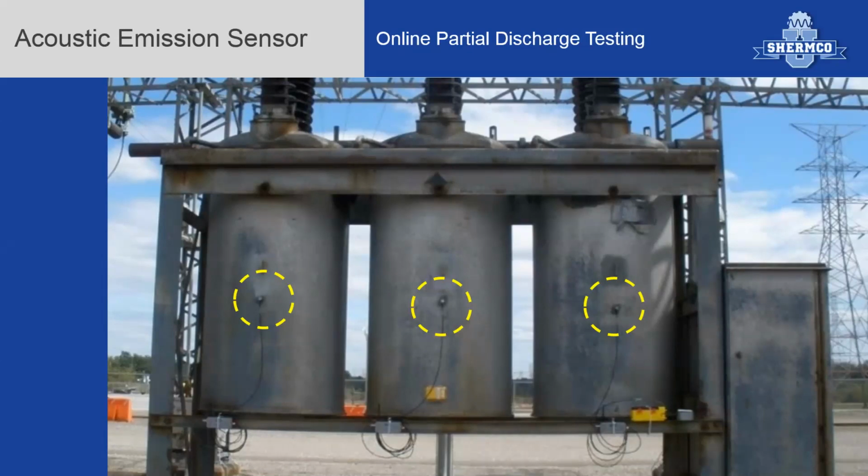Each time a partial discharge event occurs, an ultrasonic emission is produced at the site of the defect. If the defect is inside a sealed compartment, such as a transformer or SF6 compartment, the signal will usually not become airborne. In essence, it may need to travel through the media or through the oil. Now, fluid or solid dielectrics such as oil, SF6, and resins will permit ultrasonic PD signals up to around 300 kilohertz. However, air cannot permit ultrasonic signals higher than roughly 80 to 100 kilohertz.